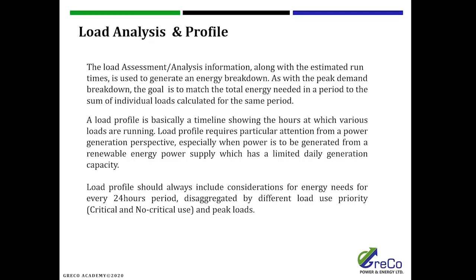Then a load profile can be investigated. We can investigate the load profile from the load analysis. Once we have the load analysis of a particular facility, from there we draw out the load profile using whatever software is available. We can easily get our load profile, which will tell us a lot about how the energy will be consumed. So, load profile should always include consideration for energy need for every 24 hours.